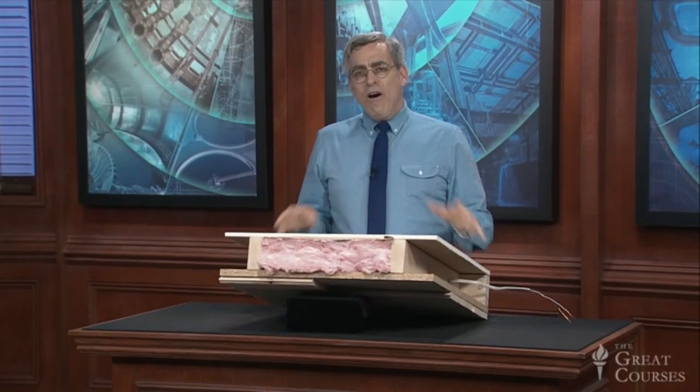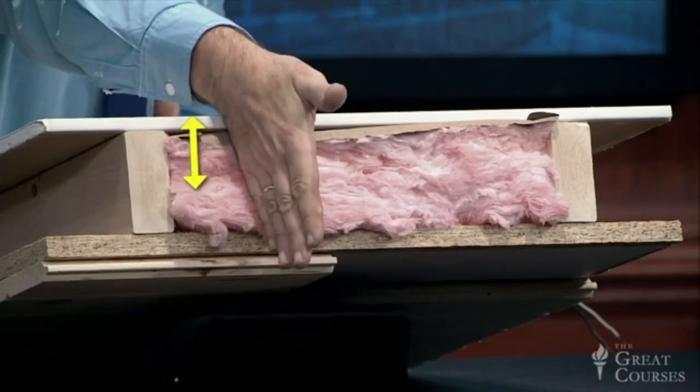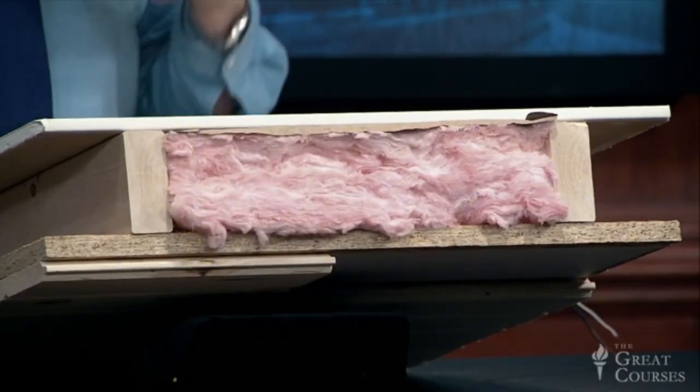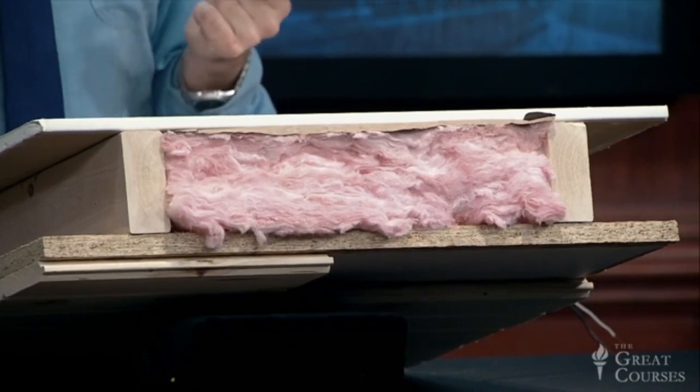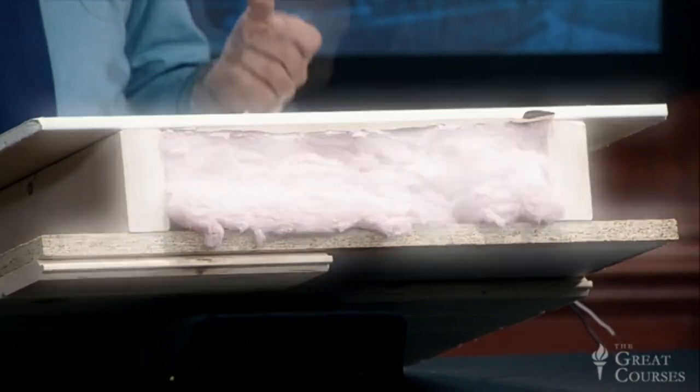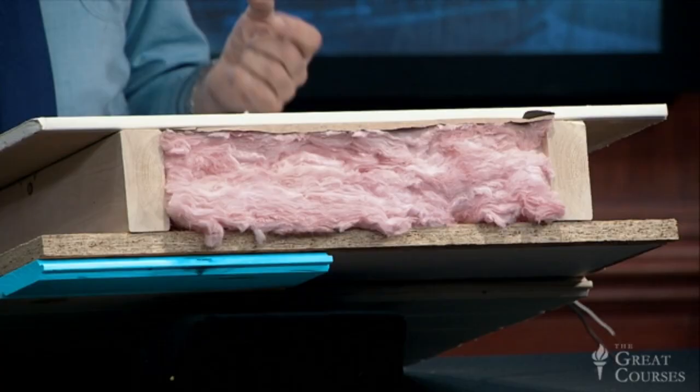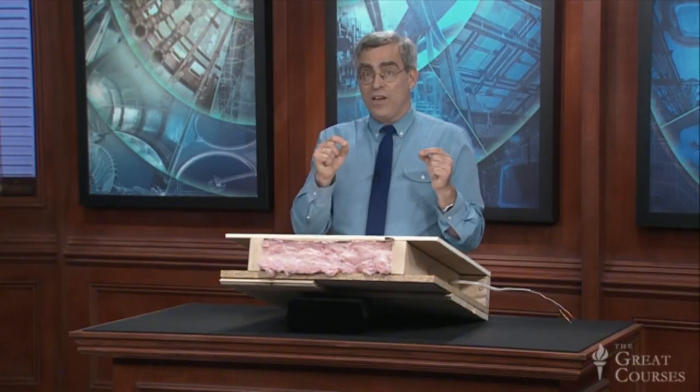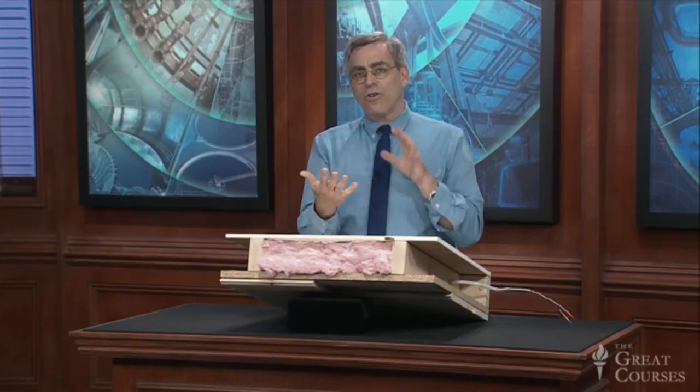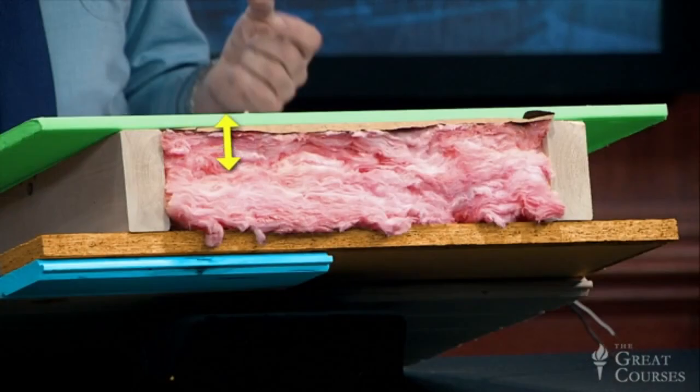And I now call your attention to this particular section of the wall. Heat moving through this section passes through, from outside to in, 3/4 inches of wooden siding, 3/4 inches of OSB sheathing, 3.5 inches of R13 fiberglass inside the cavity, and then 1/2 inch of drywall. Adding a small factor to account for the insulating value of the air layer along the external and internal surfaces, the total R value for all these materials along this path adds up to 15.6.